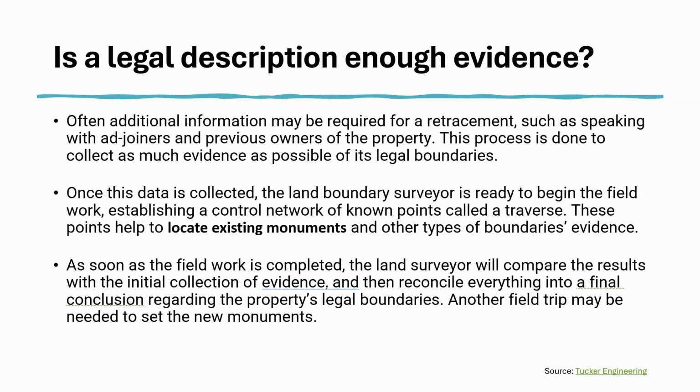And again, as soon as your fieldwork is completed, the land surveyor has to compare the results with the initial collection of evidence. You have to reconcile everything into a final conclusion regarding the property's legal boundaries. Another field trip may be necessary to set new monuments if you find out, hey, we weren't able to recover these ones, but I found the two nodes on either end of it, and from there you're maybe able to utilize something like a distance and bearing to find out where that should be, and then go back out and recheck.